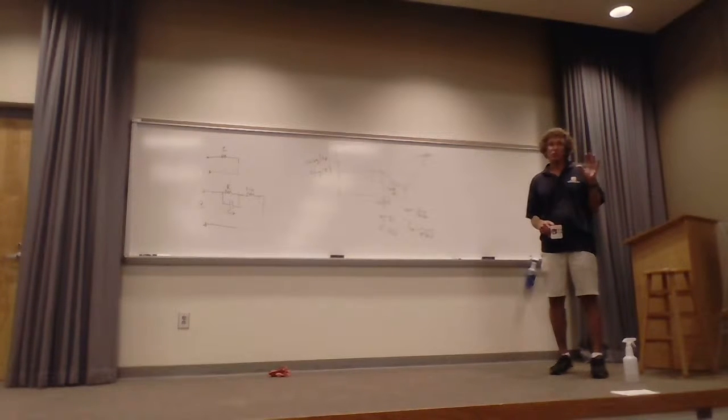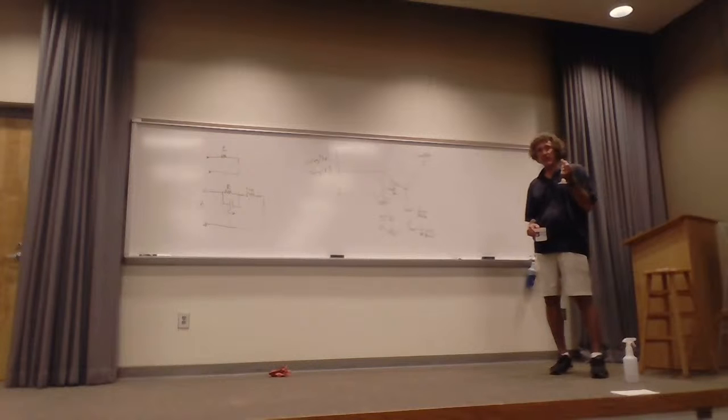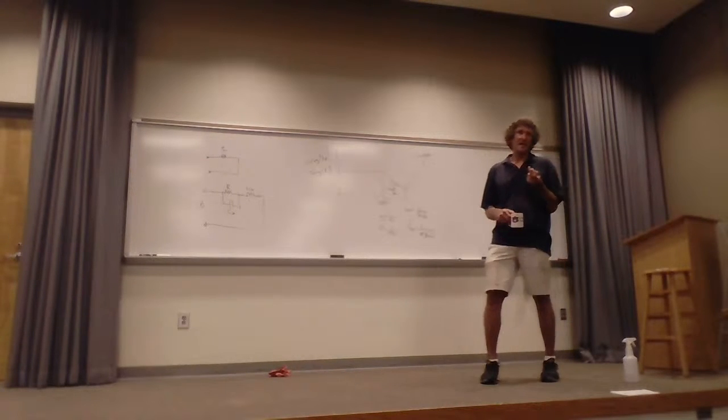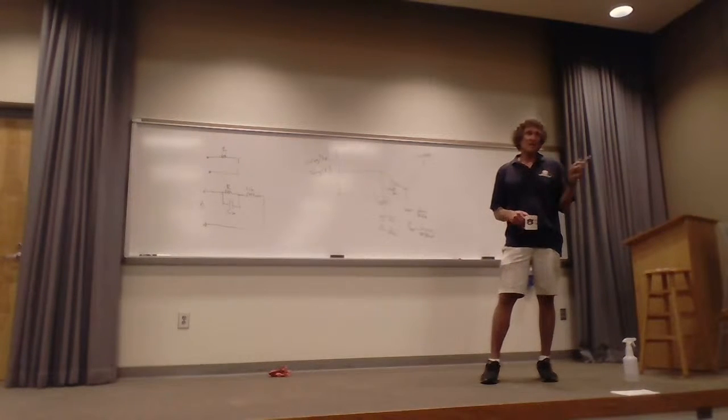What they have is a square wave generator. It's called a clock. And there's clocks all over, and they usually are between 0 and 5 volts or 0 and 2.8 volts, something like that. But they're binary. They have either no voltage or a positive value on the clock, and that is the thing that runs the JK flip-flops and is used for everything.